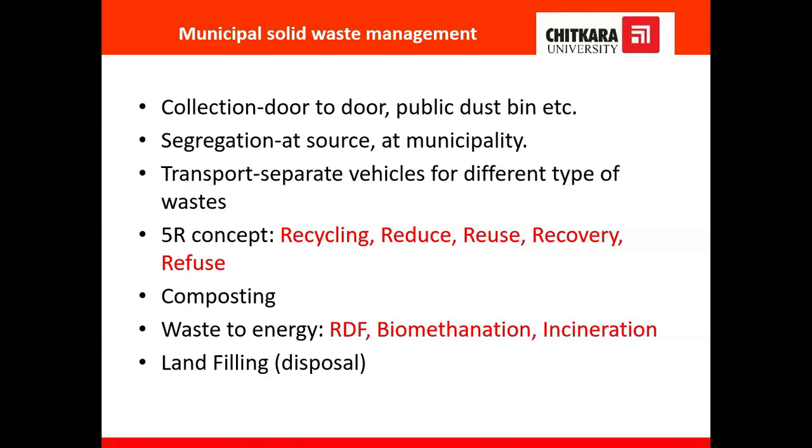The 5R concept can be promoted: recycling, reduce, reuse, recovery, and refuse. Composting: biodegradable organic waste can be converted into compost. Energy: in the developed countries, there are so many technologies because they are rich, they do not have any financial crisis, so they can derive energy using these waste materials. Refuse derived fuel, biomethanation, incineration, these are some techniques. Then landfilling, this is the final option. If we do not have any option, we can reduce the volume of that waste and finally dispose of it.